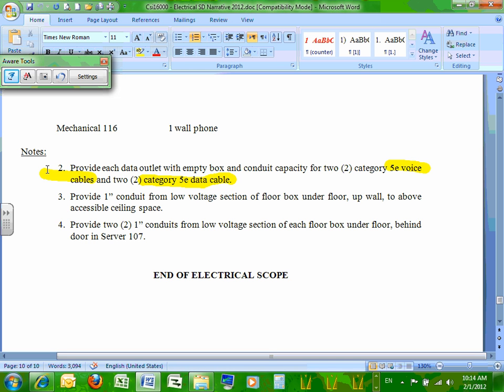And where we would address that in our jobs is in the specification, because along with drawings to each job we issue a specification, a booklet that has all of the really in-depth details, the common sense stuff to you and me, but not every contractor might know that. And it'll specify that you can't support to medium or high voltage conduit.